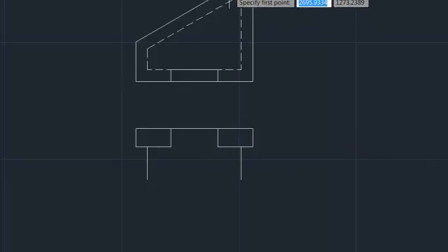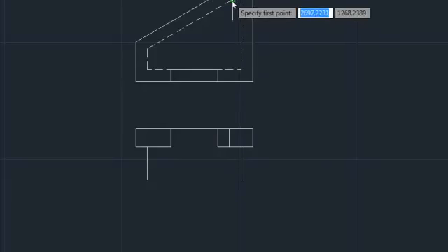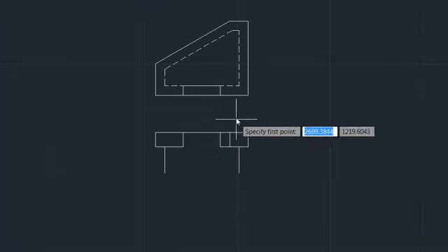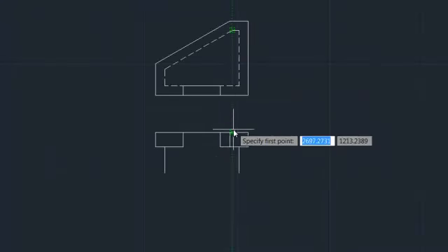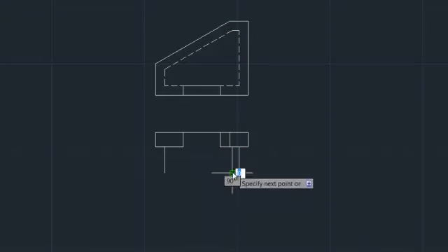Now we're going to have a hidden line from the outer edge. So if I run from that corner, hidden line on the outer edge up the top, and also down the bottom when we come to that view. But this inner edge is on a slightly different line. The interface comes along there.